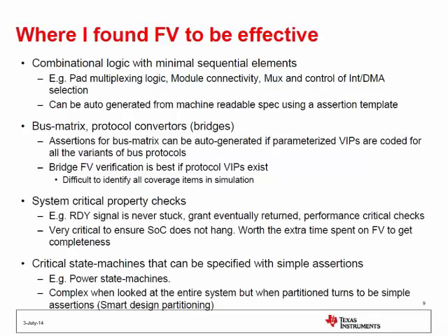Critical state machines, again, I briefly touched upon this when I mentioned clock gating, right? Critical state machines, like the power state machine, right? They are again repeatable, they are small state machines, but when you integrate everything together, you'll see that the interactions become very complex, and it's very difficult to verify all the use scenarios, how you bring up each and every submodule in a whole SoC. So there again, it's very useful.